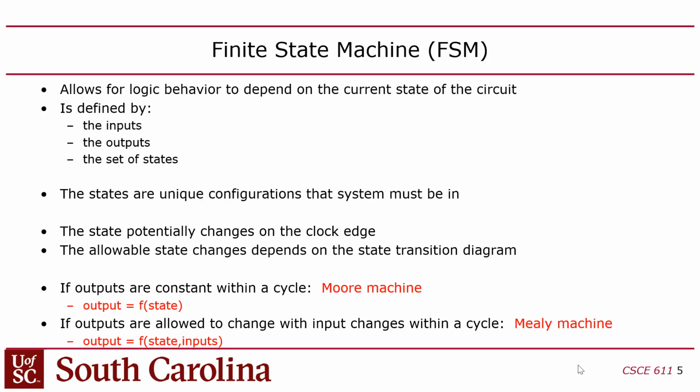And there are two styles. There's a Moore machine, where you define the states the circuit could be in. So in the case of a bus controller, your states would be something like idle, where nothing's going on. And then you may have a state that you go into if someone's requested access to you, but they're waiting for a response back, or they're waiting for it to be granted, right? Those are states. And so you define your set of states, and then the outputs of the circuit could be a function of what state you're in, in which case the outputs can only change once per clock, right?